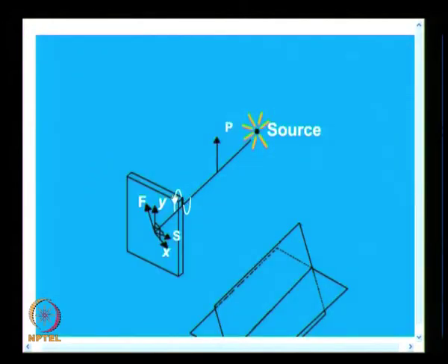So, what you have is, I have a plane polarized light, because I want to use light as a sensor. So, I should know the input light characteristic. Input light is simply a plane polarized light, and when it hits the model, when it hits the crystal plate, it is not the model, model also behaves like a crystal when it is loaded, and here we are looking at in general what happens in a crystal plate.